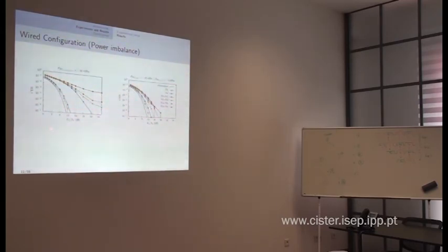The lower the signal to noise ratio, the higher the noise, right? So theoretically, for this kind of modulation, very quickly as the signal to noise ratio increases, the errors go down exponentially. And if you put one single node, then you get something pretty close to a theoretical curve.